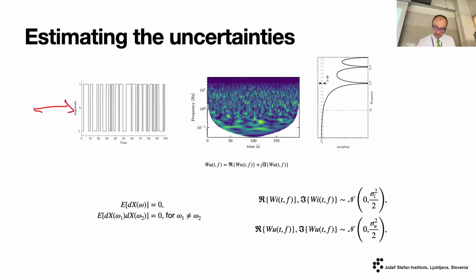So it's as if we calculate the Fourier transform for a window and draw it here, and another window, and so on. What we can see is that, for example, this frequency occurs here, but it's not present here. Then occurs here, but not present here. But if I average over time, all of these frequencies have on average the same power. This doesn't mean that they're always present. It means that they're present on average.